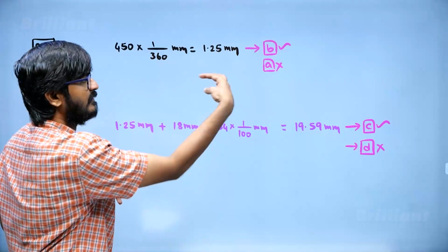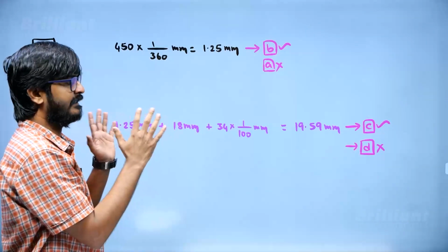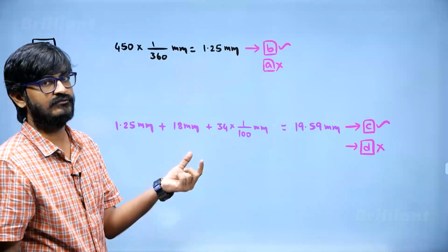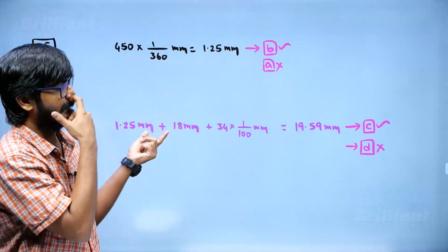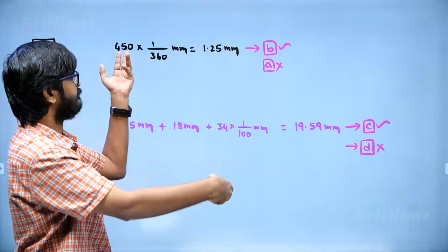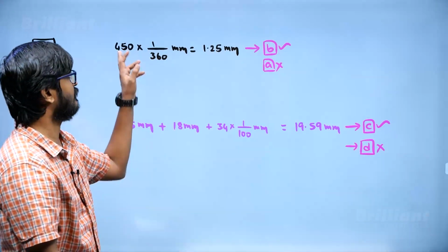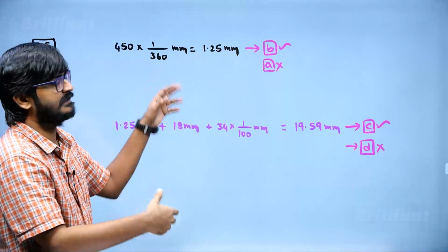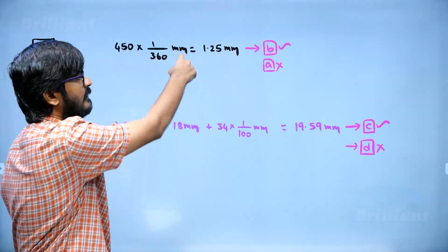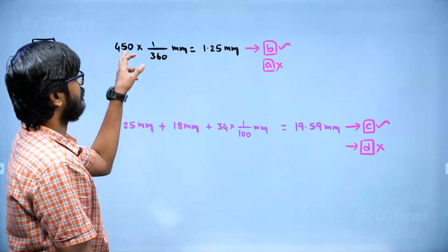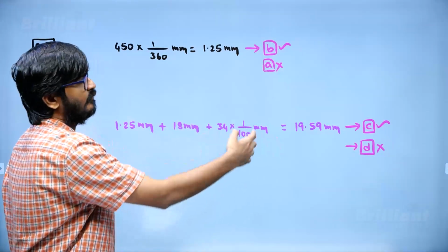So when you are rotating it by 450 degrees, then it is looking like a perfect scale, right? Let me say how much we have rotated. For one full rotation, 360 degrees, it will move by 1 mm. So for 450 degrees how much will it move by? It will move by 1.25 mm.